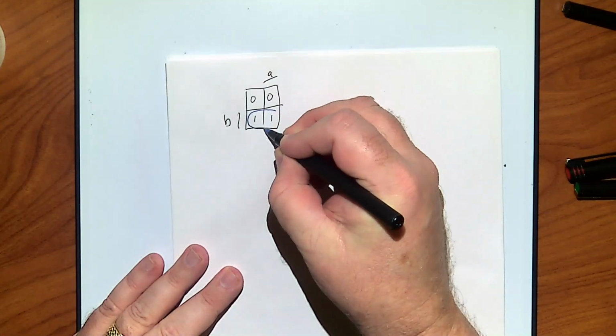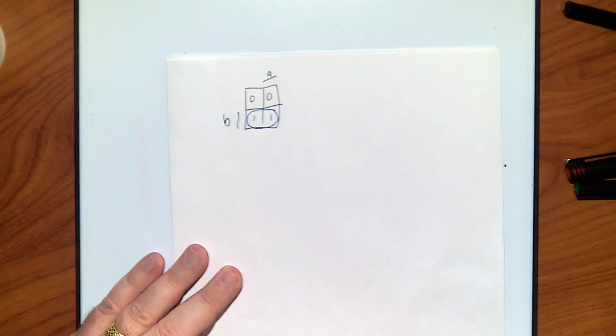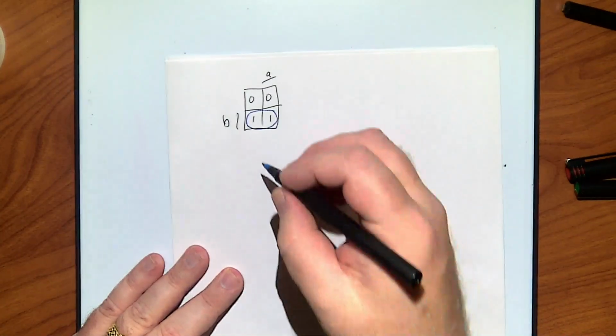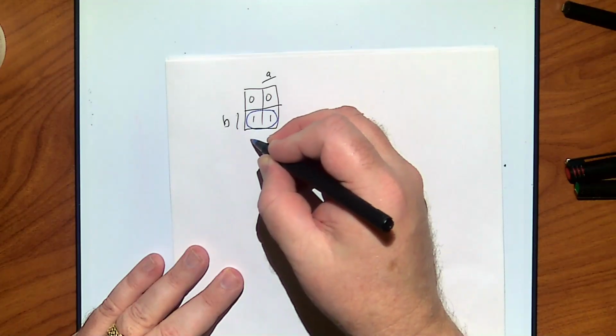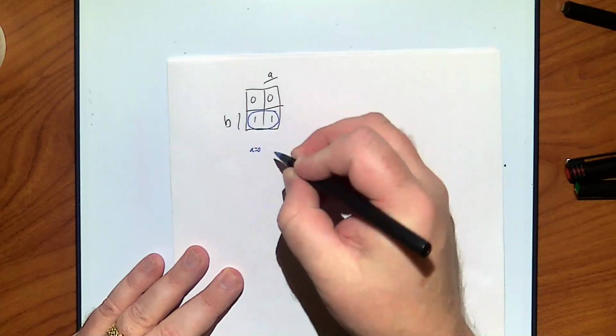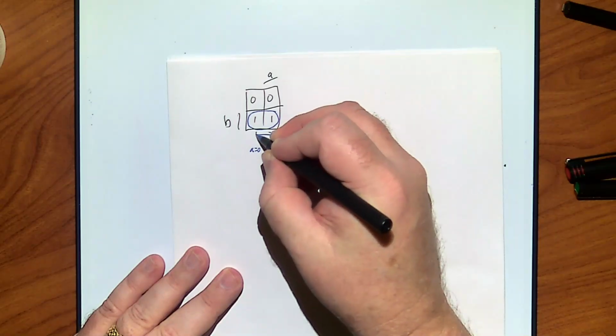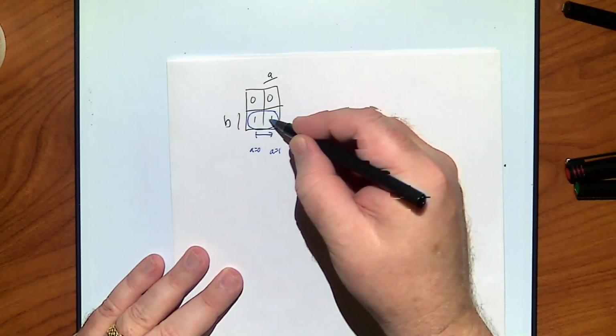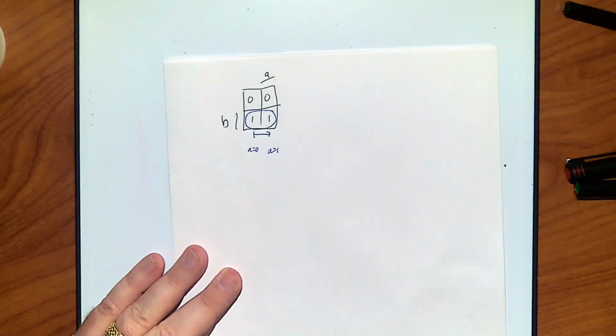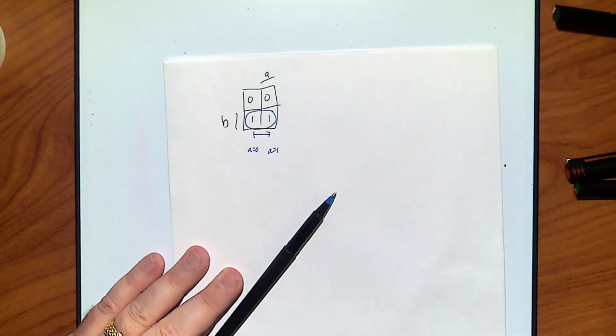A K-map is going to find the biggest encirclement. So if I was going from A equals 0 to A equals 1 in this spot, I'd be doing this transition, starting here, going to here. It's 1 the entire way. That gate always stays on, no problems.